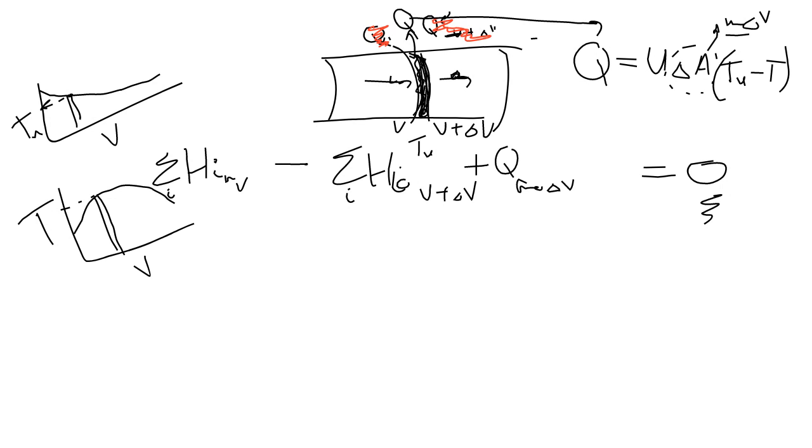So we are not making the assumption when we derive this that we've got a constant utility temperature. This is the main misconception I noticed. For CSTRs, we made that assumption that the TU is constant. Here, we're just assuming that in that small slice, it's so small that I can take the temperature of my slice at the inlet and the utility temperature at the inlet to be constant throughout that slice, or that del T is so small that it can be ignored.